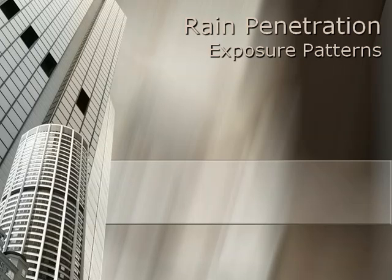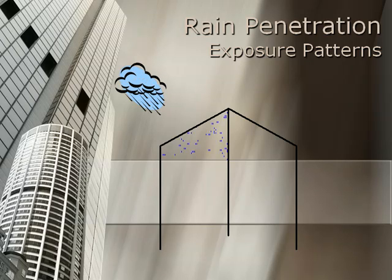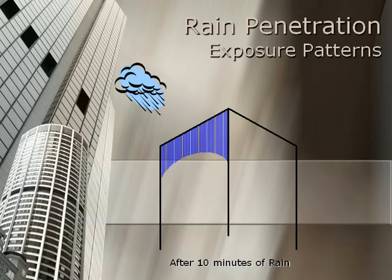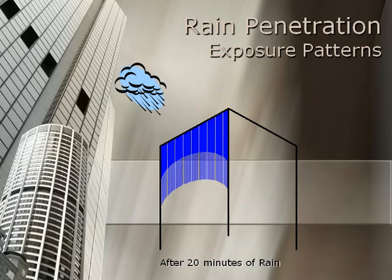Rain penetration. Exposure patterns. Some areas of buildings are more vulnerable than others to rain penetration. All openings in the wall surfaces are potential entry paths for water. At a larger scale, wind flow patterns also affect how much rain hits various areas of a building. Wind direction is a factor as windward-facing walls will be subject to more driving rain, while leeward walls will be protected. The aerodynamics of wind flow around the buildings also mean that different areas of a single wall are subject to different wind forces, especially in larger buildings where wind has to travel faster to get around the building.